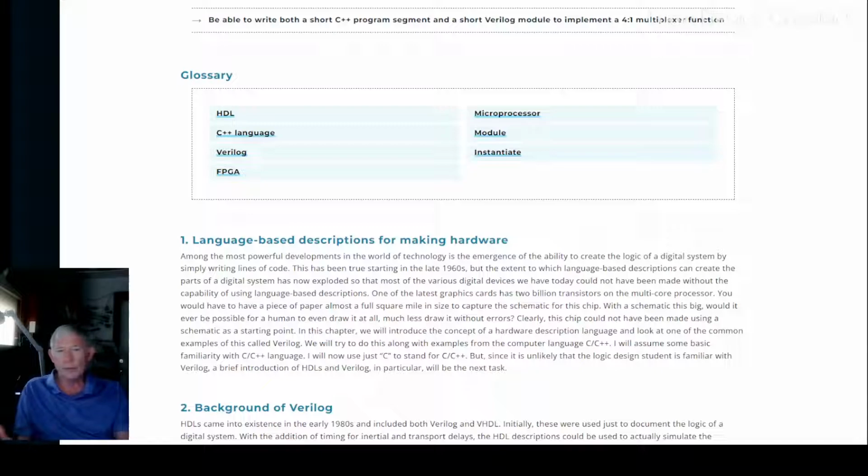So the code could be the same, and all we did was change the synthesizer in the integrated development environment, and it updates our code. So that's another real advantage: the ability to use old designs to build on the shoulders of previous designs, and to be able to manage the complexity of very complicated chips, all using these English language statements in Verilog with our fancy integrated development environments that have synthesizers.